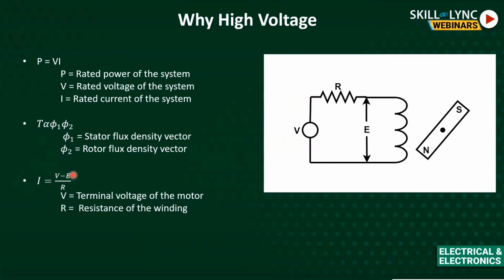And the second point is that power is equal to voltage into current. In an electric passenger vehicle, typically the voltage is between 300 and 500 volts. The reason is motor cost; it is driven by economics. A typical passenger vehicle requires around 100 kilowatts for acceleration, and 30 kilowatts to cruise at 120 kmph. The cost of the motor is most economical if the voltage is around 300 to 500 volts.